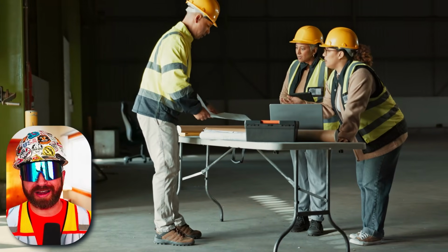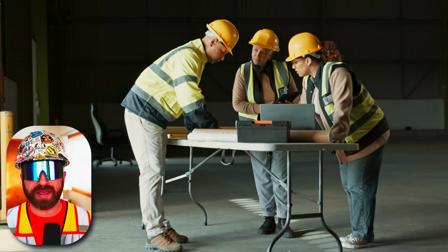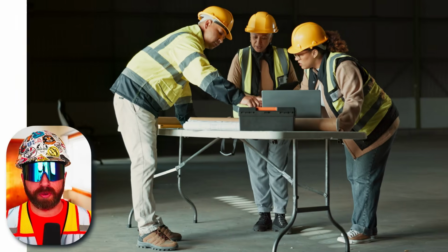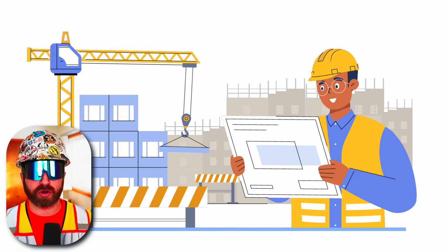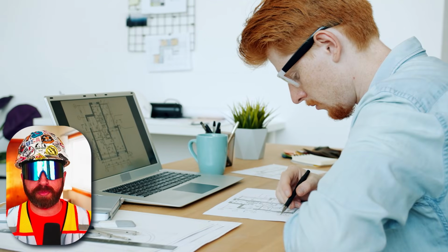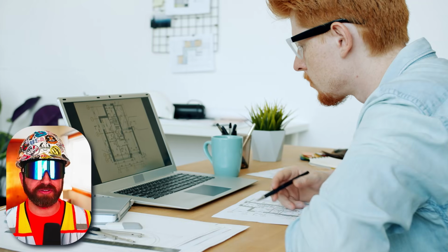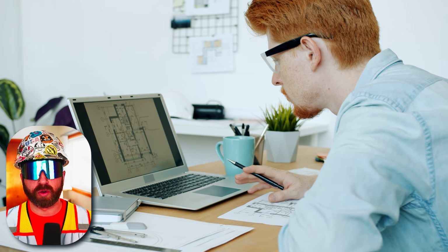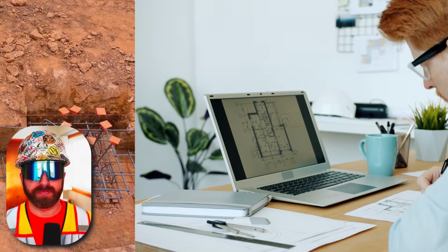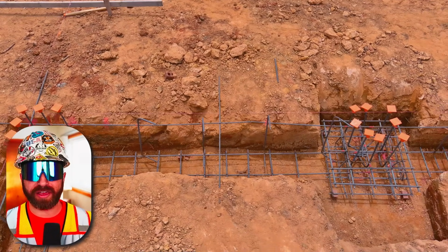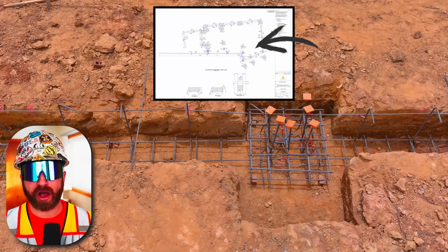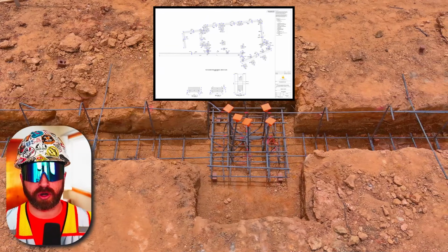So when a contractor starts on a project in commercial construction, they owe a series of submittals to the design team. As it specifically relates to concrete scope, these submittals would include information on your concrete mix design and any additives, any accessories, which could be your vapor barriers, insulation, water stops, felt at expansion joints, joint sealants, release agents, but most importantly to this video, the rebar shop drawings.